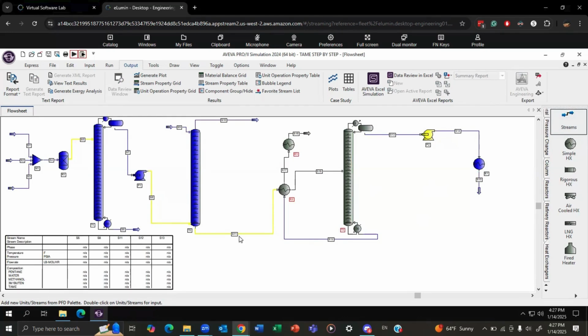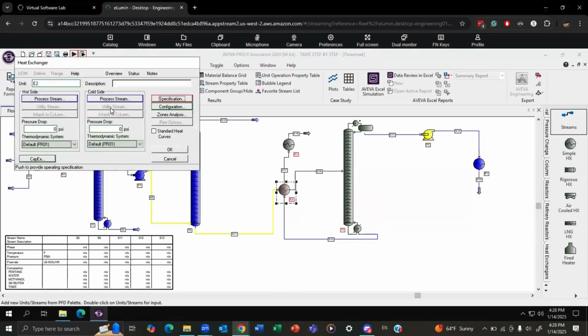So stream 11 and stream 16 are the cold streams, while stream 12 and stream 17 are the hot streams. Remember, in streams 11 and 12, the temperatures were 163.872 degrees Fahrenheit and 315.599 degrees Fahrenheit. So we want to choose the hot product temperature to be somewhere between those two values. We'll choose 300 for our case.